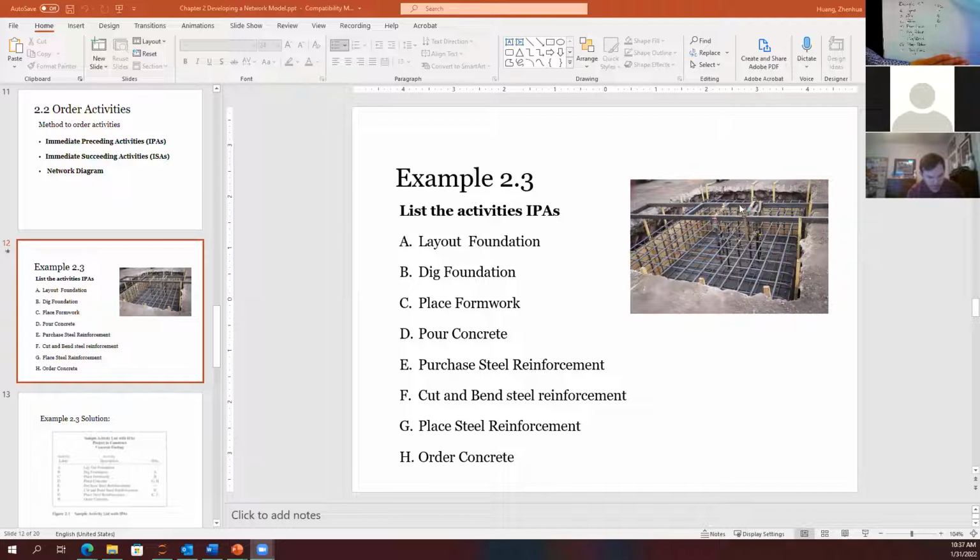So which one happens first? Should I put formwork first, or should I put rebar first? The formwork first, and then put the rebar. If you put the rebar first, then the formwork is hard to insert over there. And if you want to put formwork, it's easy. It's still empty over here. Put the formwork on the side and then put the rebar.